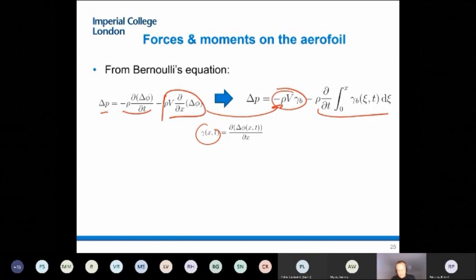The second term says that we have an additional term associated to the inertia of the flow which is moving. That's what we refer to as apparent mass. It's linked to the acceleration of the flow. Acceleration generates a resultant force in Newton's momentum equation, and that one cascades into a pressure field which is proportional to the rate of change in time of that circulation. These we call circulatory effects. These we call apparent mass or added mass effects.